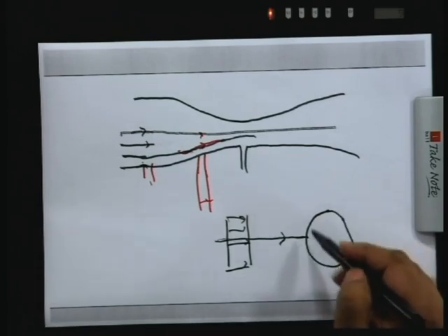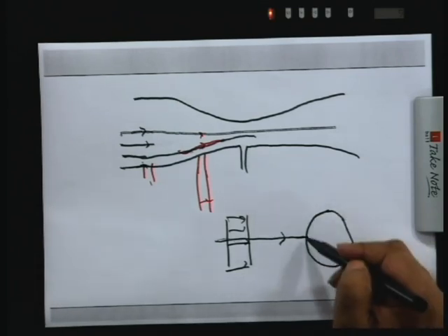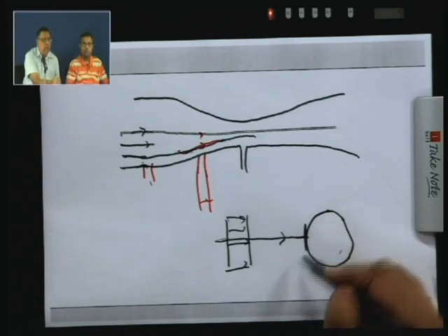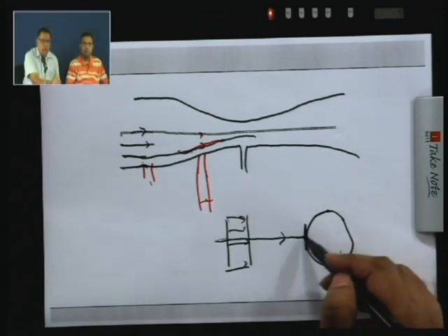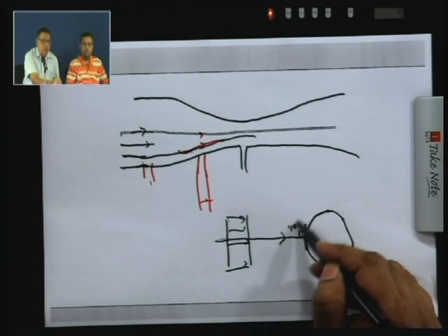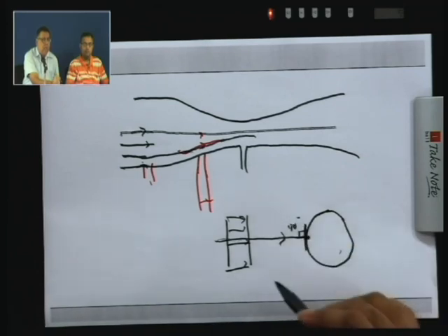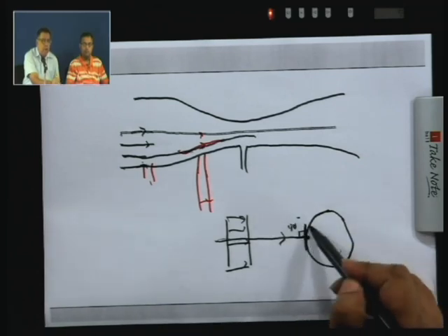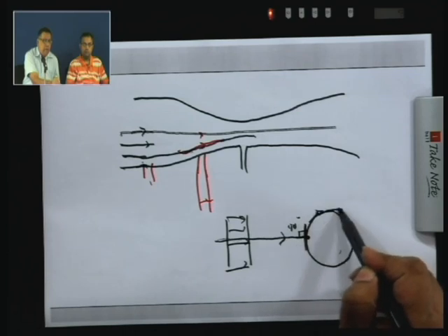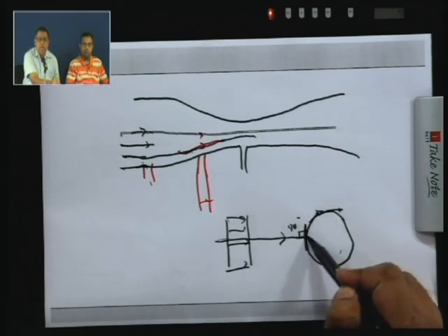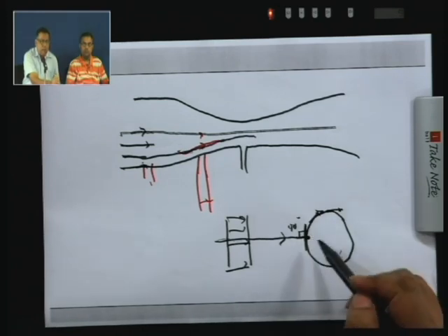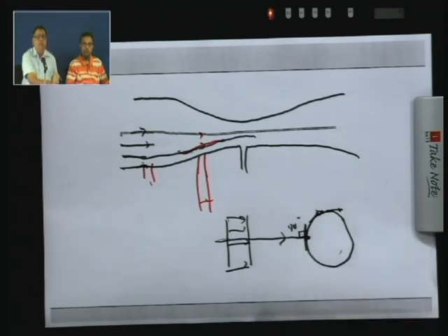The wall is also a streamline because it is impermeable, and you have another streamline perpendicular to it. This tangent is at right angles to this. So this is a stagnation point, and if you consider inviscid flow, the fluid velocity along the surface may be non-zero, but at this point it will be 0. Otherwise there will be two tangents. So this is an example of a stagnation point.